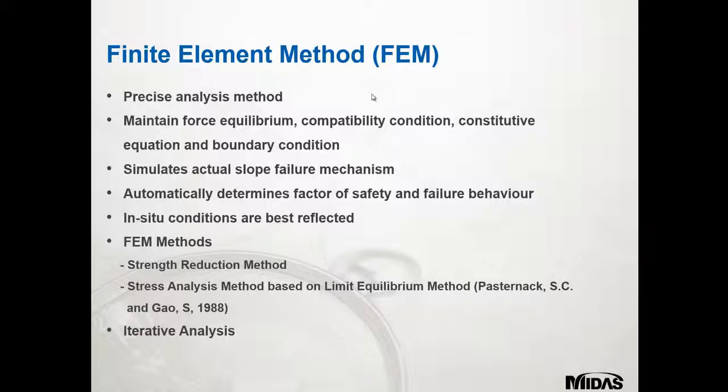Among these methods, finite element methods are most widely used to solve slope stability problems, assuming that the material is continuous. The finite element method gives more precise results, as the analysis maintains force equilibrium, displacement compatibility at each node, constitutive equations to model linear elastic, non-linear elastic, and elastoplastic material behavior, and the boundary conditions.